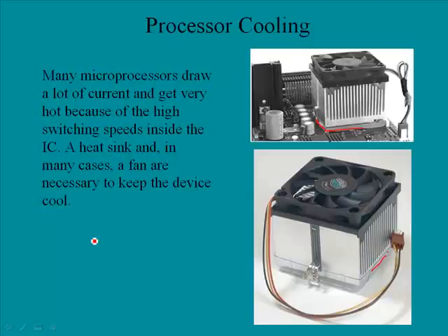And so a common fault that occurs is that if a computer is turned on and after maybe 2 or 3 minutes it just shuts off for no apparent reason, oftentimes the problem is found right here, that the fan is not functioning. And so as the temperature comes up, the thermal temperature reaches a certain point and the machine just powers off. Now that's if you're lucky. If it doesn't power off properly, then you probably have a toasted processor.